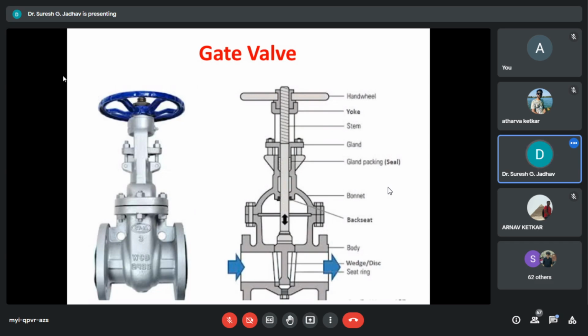For large diameter valves where the operating torque is high, gear arrangement is provided to facilitate operations. Mostly bevel gear equipment is adopted. So we can recommend specifying gear operators. Valve rating: here class 150 and size 40-inch NB and above. Class 300, 12-inch NB and above. NB stands for nominal bore. And class 600 and above, 8-inch NB and above.